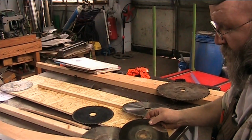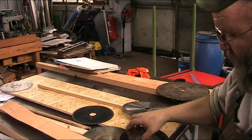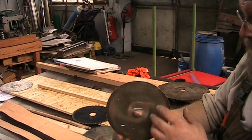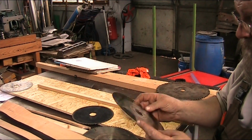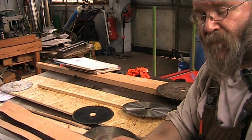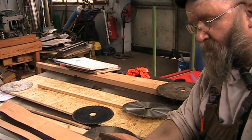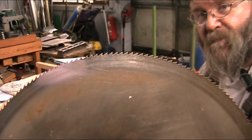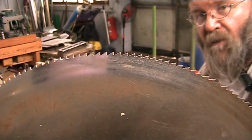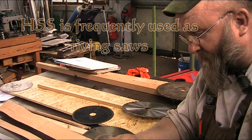So the next blade we're going to take a look at, we have some veneers, and so here's another rule of thumb: the thinner your material is, the finer the tooth spacing is going to end up being. Now, if any of you have ever worked with veneer before and used hand tools, the veneer saw has a real fine tooth, and so does this guy here. So let's bring this real close. This is only like 1/8 inch spacing on this tooth, and this is an HSS blade.